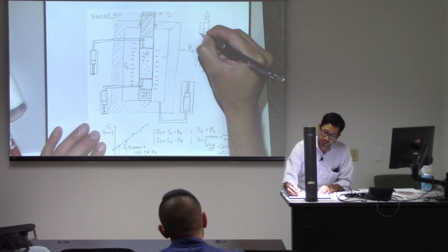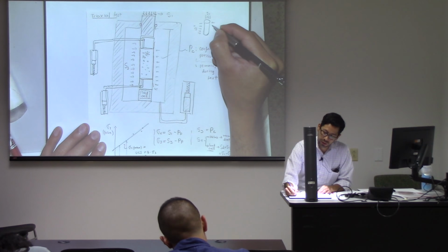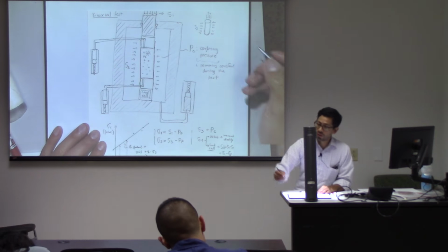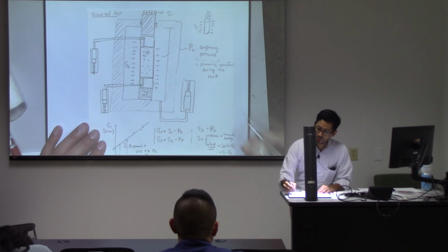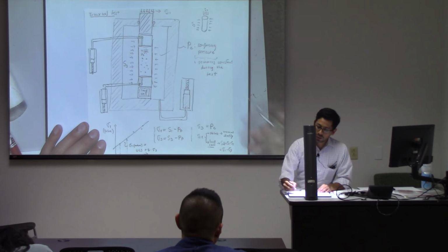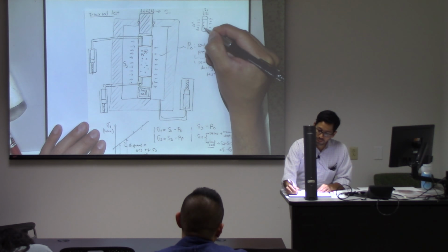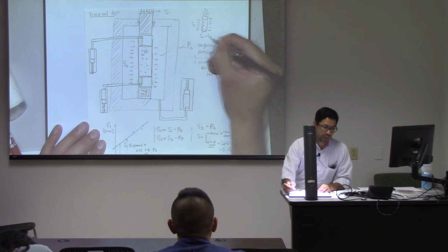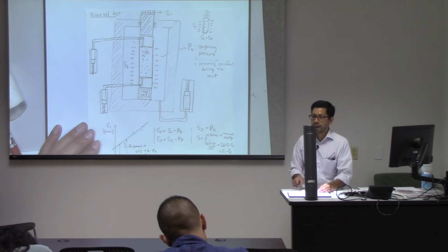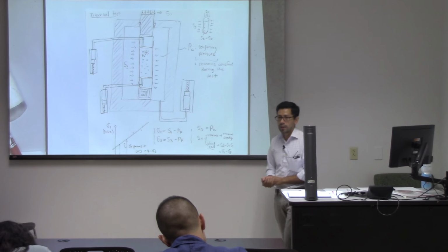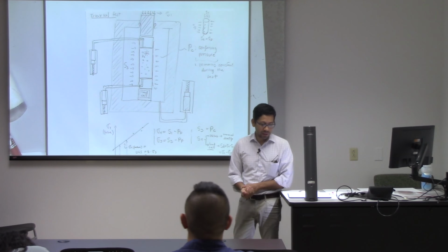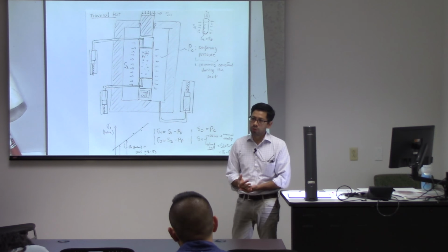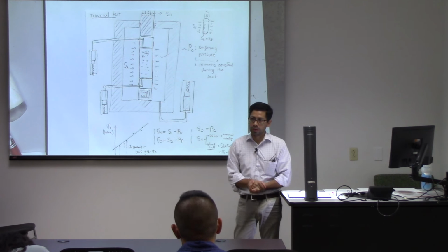Usually I just draw S3 on this direction, but all around the rock there is going to be stress as well. So the intermediate principal stress, or the stress perpendicular to this direction, S2, is just going to be equal to S3. So because of that, in these kind of cylindrical axisymmetric tests, we don't talk about S2, we just talk about S3 because S2 is equal to S3.